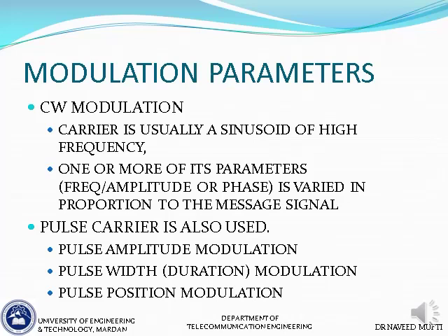When it comes to pulse modulation, we've got three main types that we have studied in communication systems. Those are pulse amplitude modulation, pulse width or pulse duration modulation, and pulse position modulation. And all of these we have studied in communication systems. So they basically form part of what we call analog modulation schemes, because the data that is modulating the carrier is analog in nature.